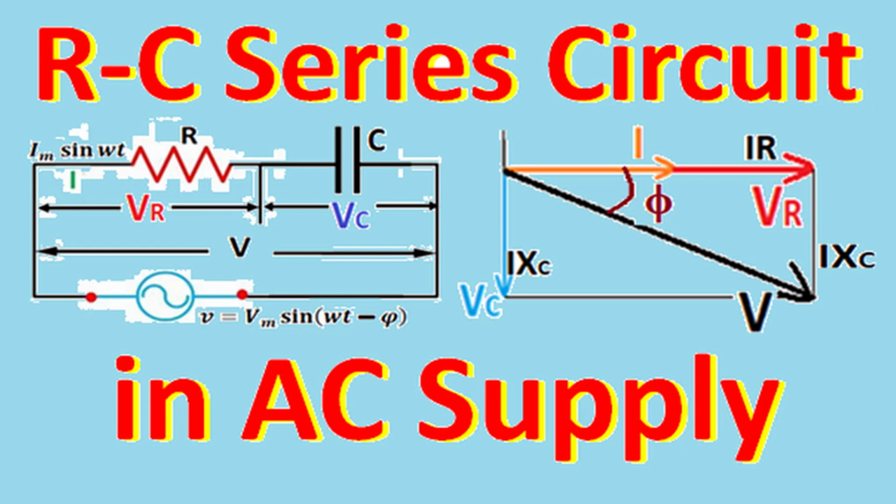Today in our playlist, Basic Electrical Engineering and Class 12th Physics, we'll understand RC series circuit in our chapter Alternating Current Circuits, and we'll understand that in an RC series circuit, voltage of resistance is in phase with current phasor and voltage of capacitor lags current by 90 degree, and phasor summation of resistance and capacitor voltage would have a certain lag angle between 0 and 90 from current phasor.